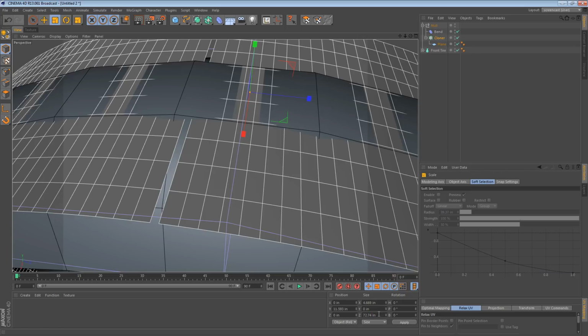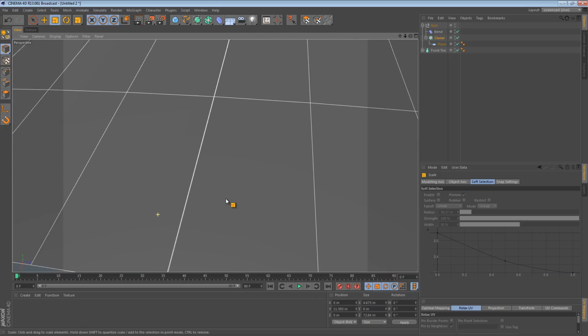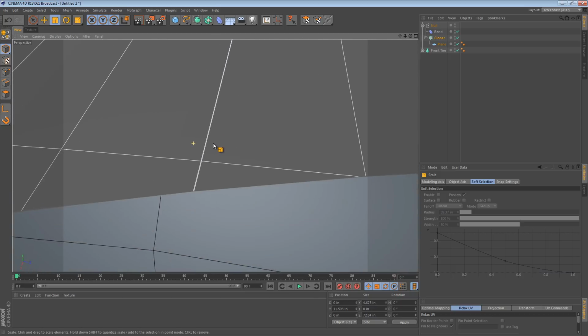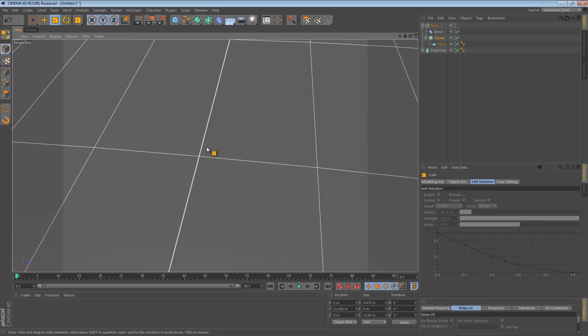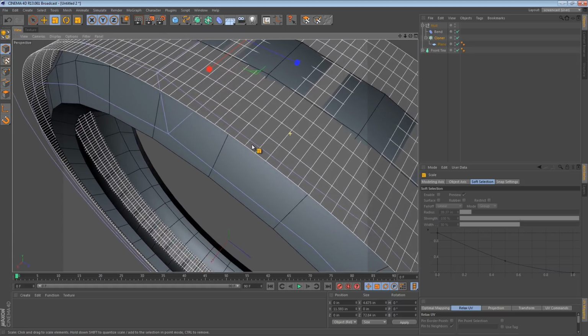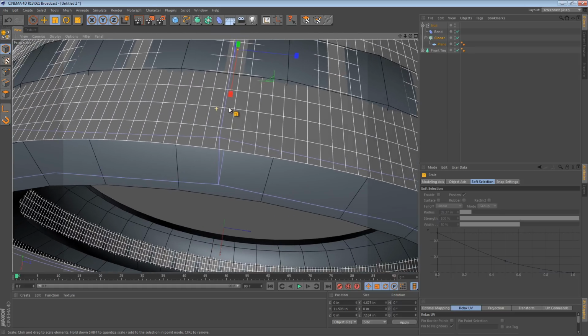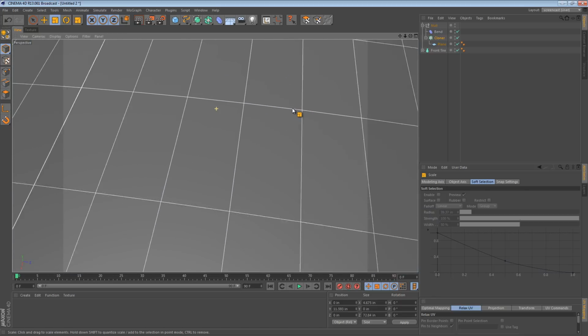So we can go 0.4, got a little bit closer, let's try 0.84. It looks like it's almost there. Let's go 0.83. Yeah, so it looks like 0.84 gets us right up against the edge of it. And we're still not perfectly lined up. There's a little bit of a gap, but that's okay because we have gaps everywhere. Each one of these objects is not joined to its neighbor yet. Let's see how we can actually do that.